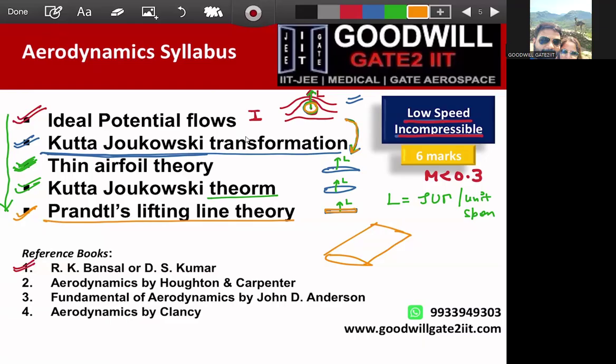And then with the help of lifting line theory, you convert that airfoil into a wing. And that's how the wing will produce lift in the end. Now, in the process, you will learn many things. What is elliptical lift distribution? What is lift curve slope of an airfoil, lift curve slope of a wing? And in this, you will also learn about what is known as induced drag.